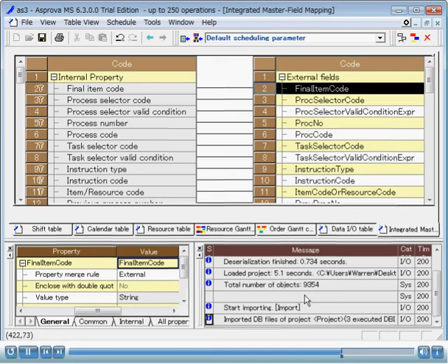You can click the right mouse button and select Link by Position from the pop-up menu, which is applied to the empty area located between the internal property and the external field in the field mapping window. You can reflect the setting contents onto the system by clicking Apply from the pop-up menu. This is on the condition that you have performed the mapping properly after verifying the mapping results.